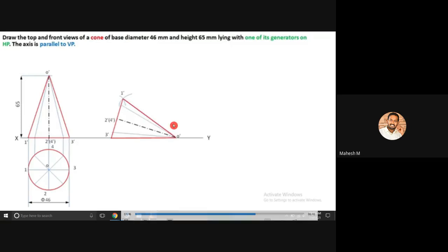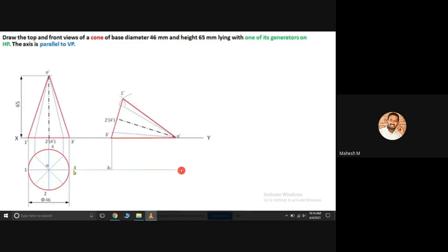Okay. So next you can project the points from the base and you can project the point from the apex point. So you'll be having a vertical line and also you have to create the horizontal line from our previous problem. So now you will be having 8 points. Here also you'll be having 8 points. So each point will have a horizontal line and each point will have a vertical line. So here it is a vertical line of 3 1 dash and here it is a horizontal line of 3. Sorry, 3. So the intersection can be marked as 3 1.